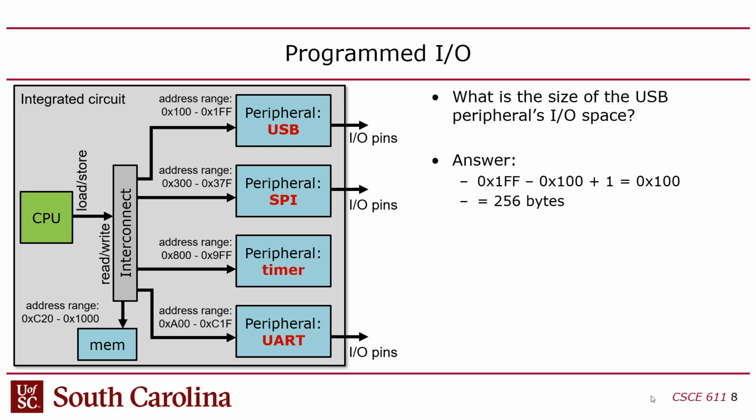Now, why is that? Well, I mentioned that the ESP has 48 total pins, 40 of which are programmable. 40 pins is not enough to do a parallel protocol, because a parallel protocol needs 32 pins just for the data alone, and then additional pins for control and addressing and that kind of stuff.